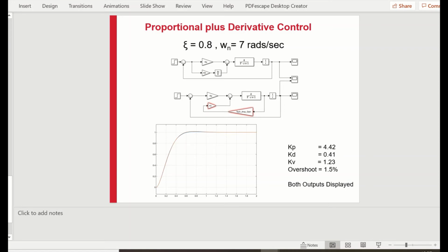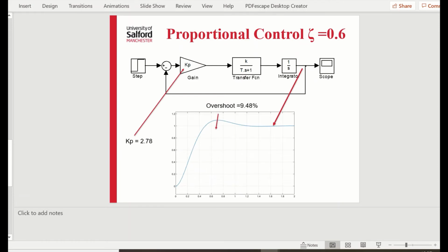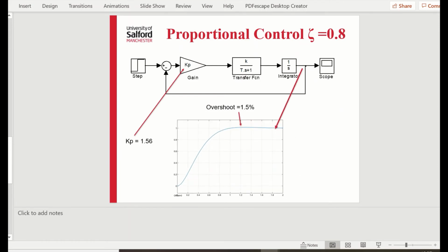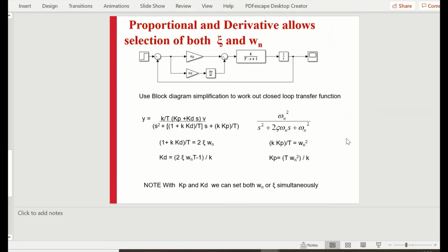We just go back quickly to the proportional control at 0.8. This is just proportional control. Notice the peak overshoot here is about 1.2 seconds. So with the derivative, it's really sped up, and we've got it to come up at 0.8 of a second. So it's quite a bit faster. It's almost 50% faster, isn't it, with the PD? So the PD is doing better than the proportional. So that's why you get a faster response with your PD than you do with your proportional. So that's why it's attractive to put that extra signal in here, because you can get more out of your servo.